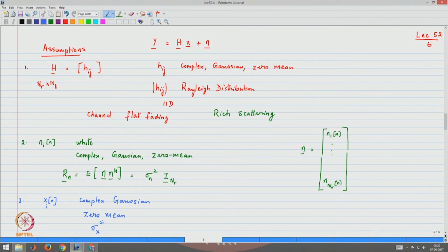Again, the reason for this will become clear when we talk about the description or the calculation of capacities. So, we have made 3 assumptions, all of which are pointing to Gaussian assumptions. In this equation, the channel gains are complex Gaussian, the received signal noise samples are complex Gaussian, and again the third assumption for the purpose of capacity calculations will be the assumption on X.